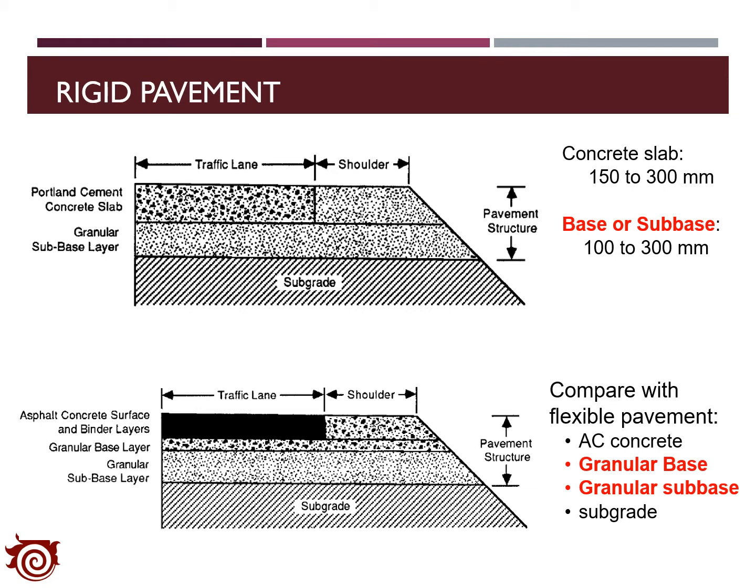In the 1960s, PCA boasted that the rigid pavement did not need a granular subbase, and they designed the Highway 401 with this assumption. Ideally, the highway is designed to work for 40 years, but only after 5 years, there were a lot of pumping issues along the road. And this verifies the importance of the subbase layer to support the rigid pavement.